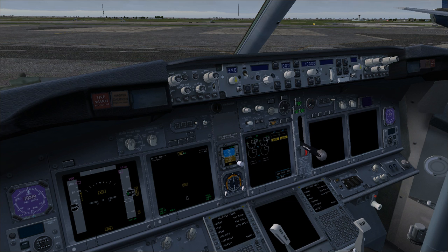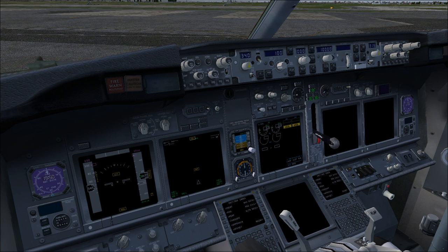Now I will connect the ground power and go for all the screens to give you more information about them. Okay, now we are on AC power given by the ground power switch, and as you can see we have only 3 screens on. This is because the right DU unit takes approximately 1 to 2 minutes to start up after initial AC loading. This is because of the avionics configuration, but those screens will come on very soon.